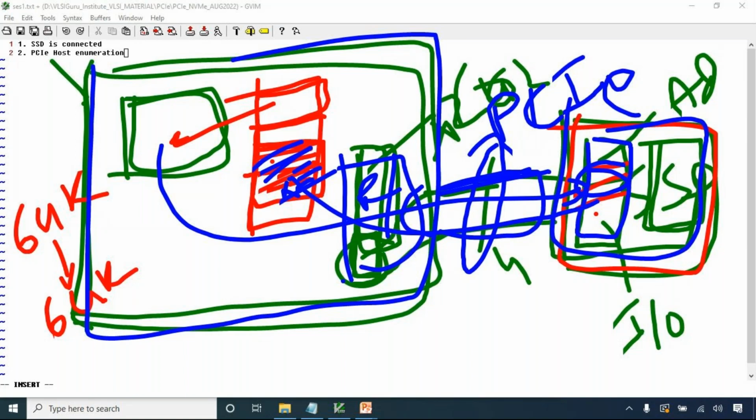Now, to place one command, which is how many bytes in size? 64 bytes in size. How many locations will be used, assuming that my memory is byte addressed? Each command will take 64 address locations. To place one command, I will use 64 address locations. To place 4000 such commands, 4096 commands, it may use 4000 into 64. Some space it will use.